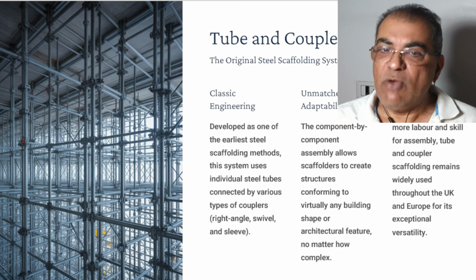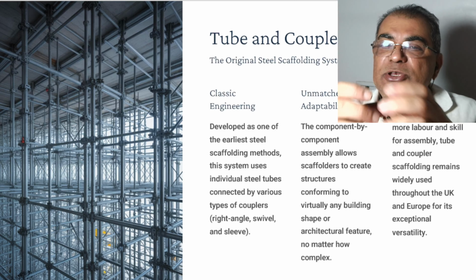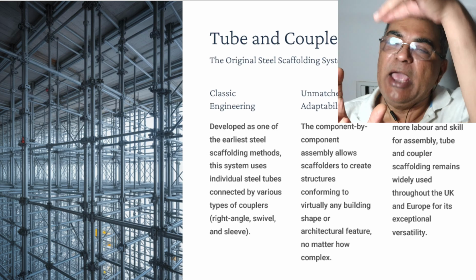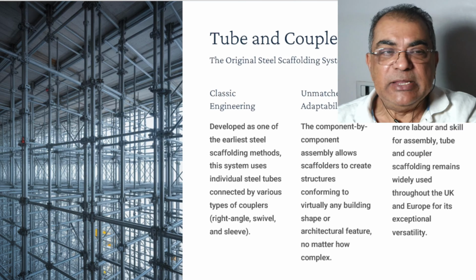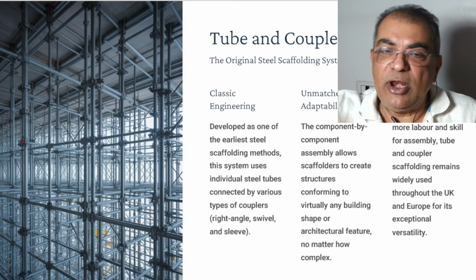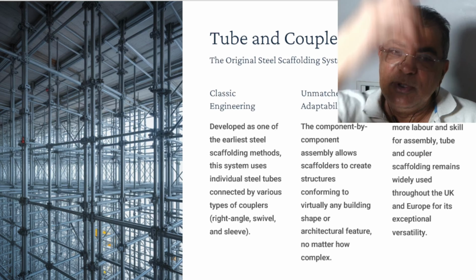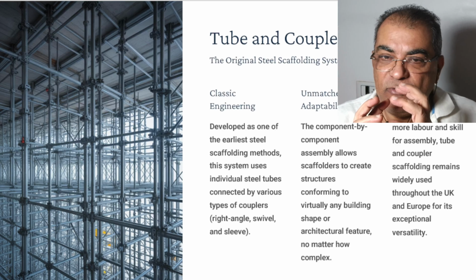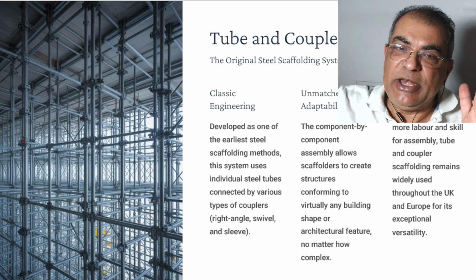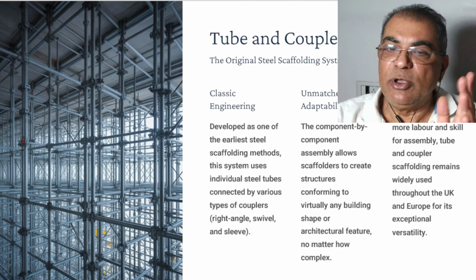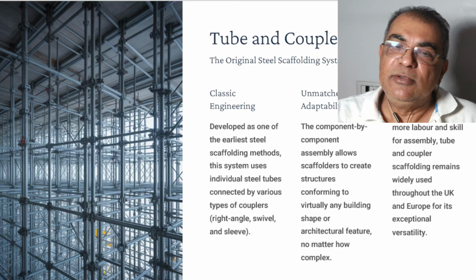Now, one type of scaffold is called the tube and coupler scaffold. Tube and coupler means it is prefabricated. At every distance there is a coupler system. In the other type there is a swivel clamp, wherever you want, on a straight simple pipe, but this is not a simple pipe. It is a built-in coupler system. The other is Layher. You just have to click it because it is very fast. You can erect it and dismantle it very fast.